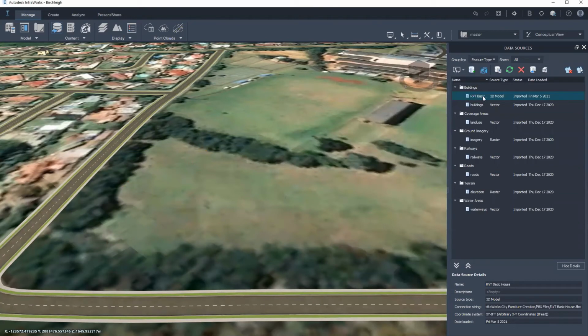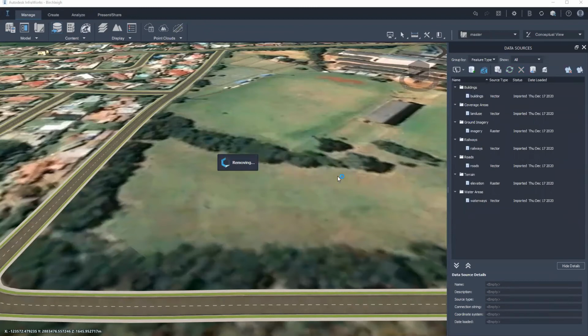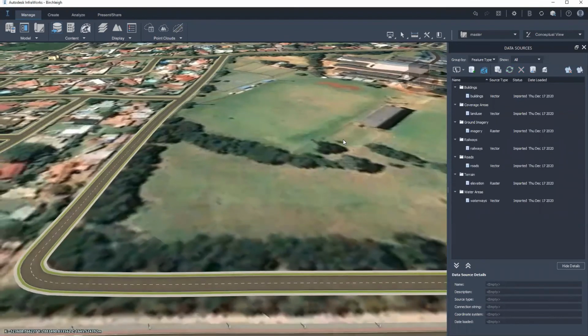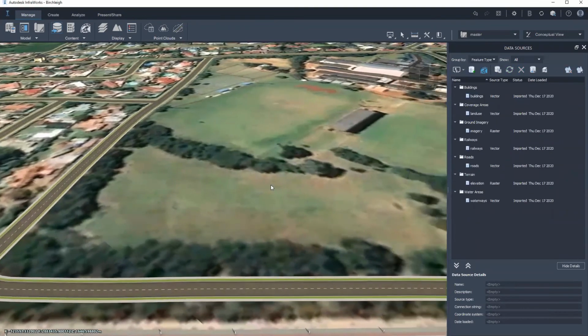And now to show you that it actually worked, that the import or the placing it into the catalog actually worked, I'm going to remove this data source from buildings. Oh, and please note that once you set your type to buildings, it will automatically move the model over to your buildings section over here. But we do not need this model inside of our drawing anymore. So I'm going to remove that link completely. As you can see, it's not in there anymore.